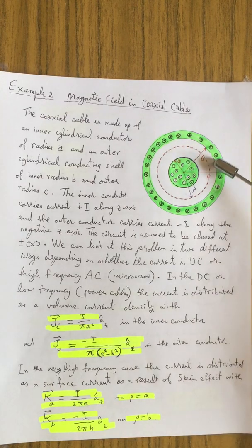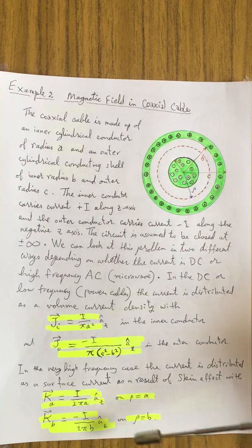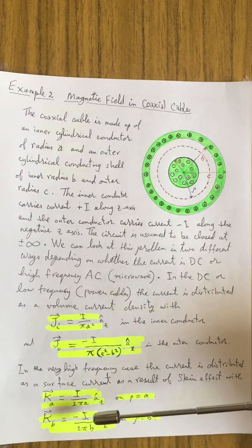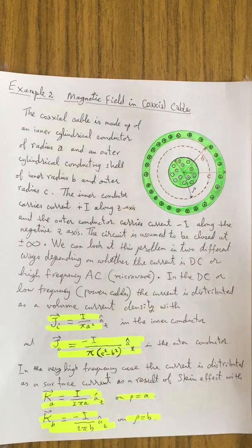And we have the current density on the inner surface of the outer conductor. It's on the inner surface because of the attraction of the two. In electrostatics, you had this, for example, plus rho_S, and here it will be minus rho_SB, here rho_SA, and here rho_SB. But here, it is the current, charge in motion. So it is minus I divided by the perimeter 2 pi b, at rho equals b.